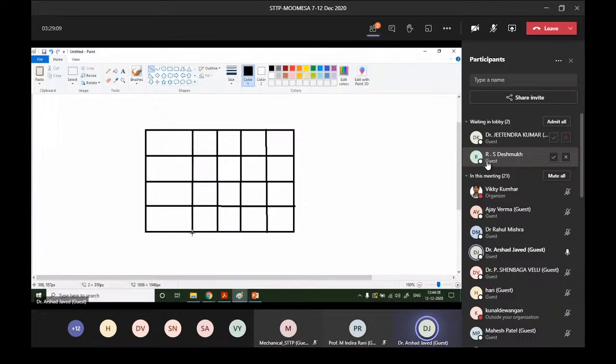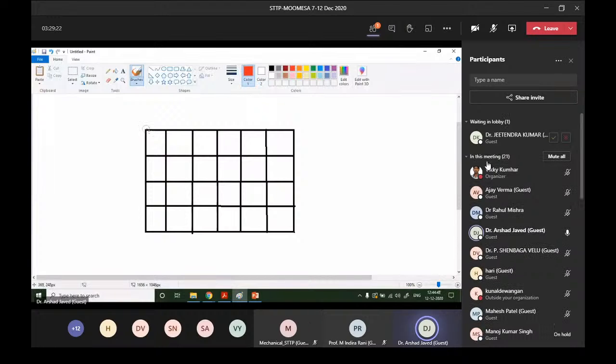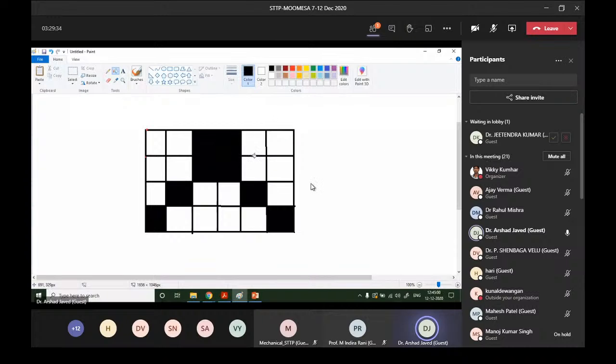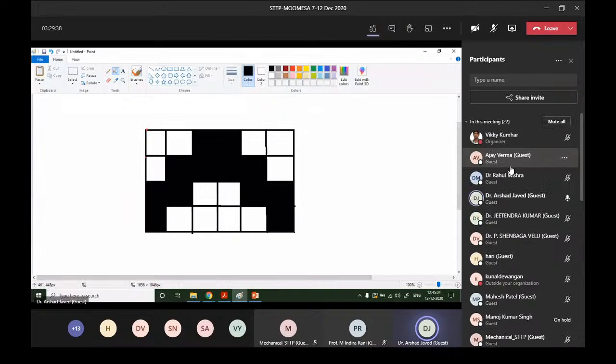This is done using the discretization scheme in FEM. And then after that, in FEM terminology, these are the nodes here, defined nodes. And then you can define the material: material is here, material is here, material is here, and so on. So now you have a rough sketch of the beam which may look like this.